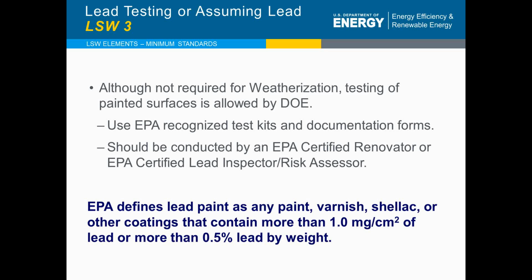And an important point here is that testing is not required, but if testing is not done on a pre-78, then you must assume the presence of lead with the work that you're doing and apply all lead-safe work practices. Okay?